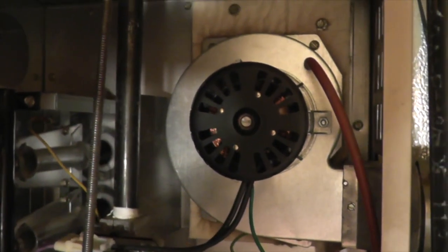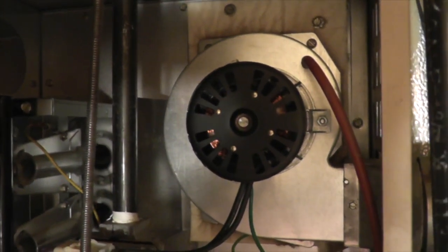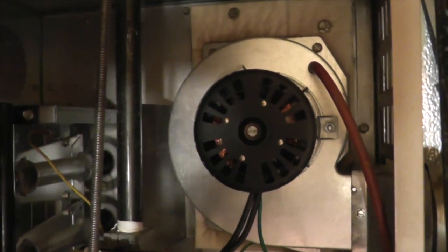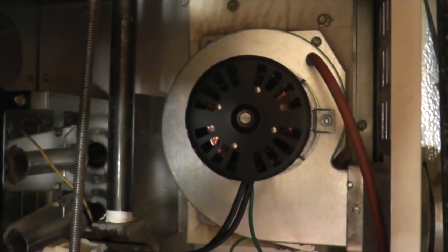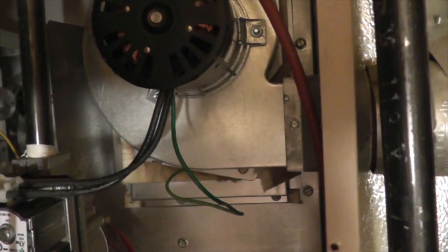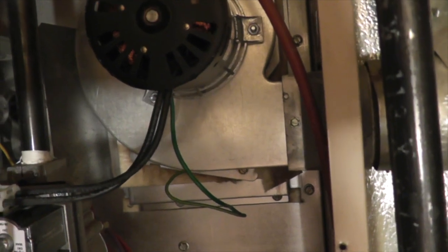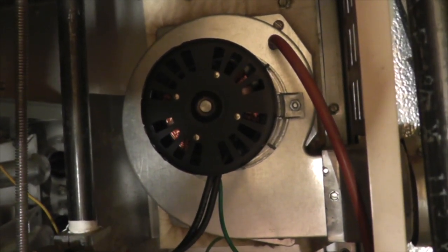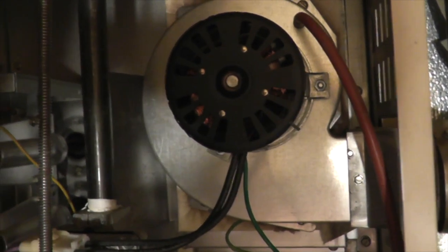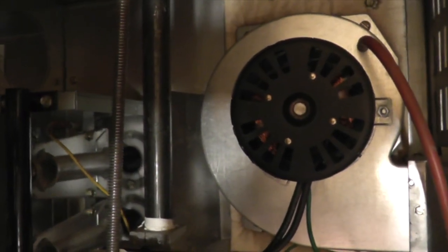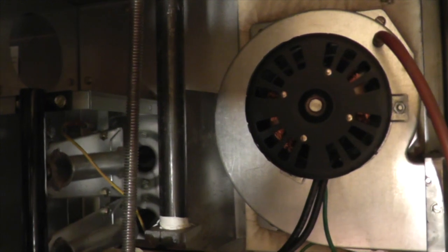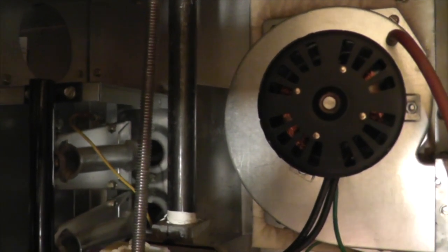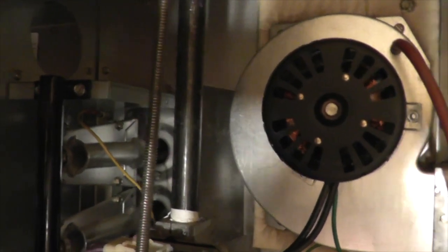And okay, I went ahead and replaced the induced draft fan. Really easy job. There's a total of about 4 screws holding it on, and another one on the exit going out the stack there. Just pull off the hose and connect it back up afterward. And that was about it. It was 160 bucks shipped, and not too bad. About a third of the price of having someone else come out and do it for me.